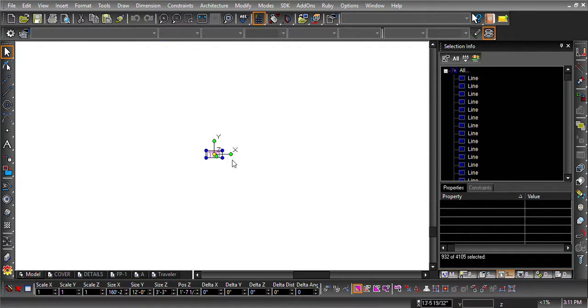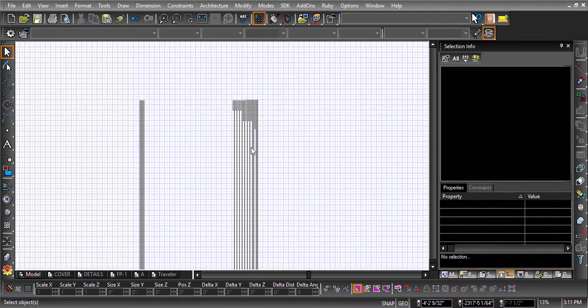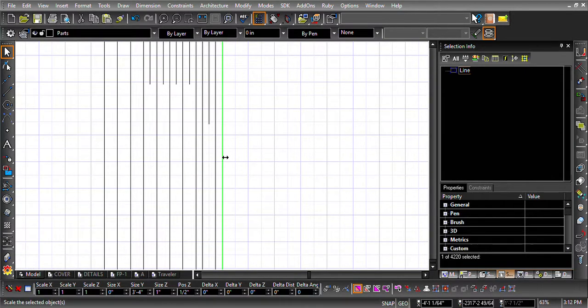That's why we've got to get to it. We've got to explode it, so that instead of being a group of graphics, it's all one panel. Now it has the information about that particular piece. So this line that I just selected, these first four, I think it's 4 or 5 lines, they're panel metrics. I'm storing information in these that are information about the panel.